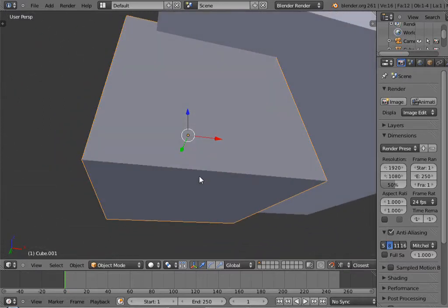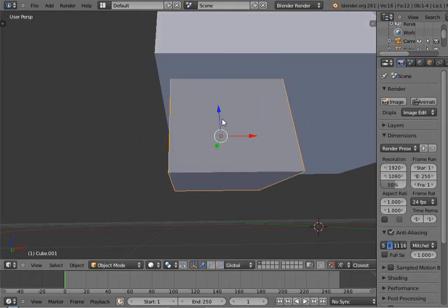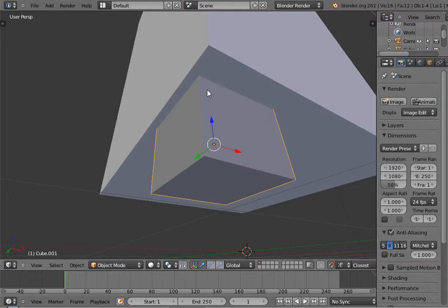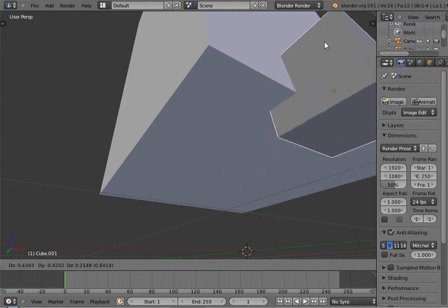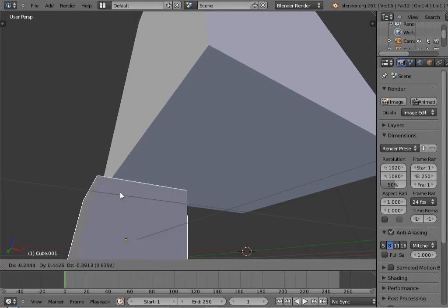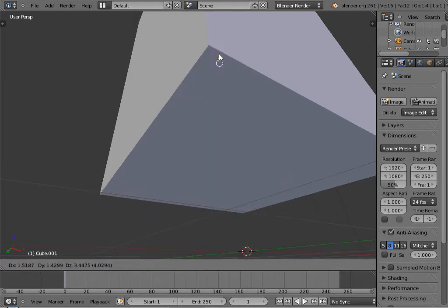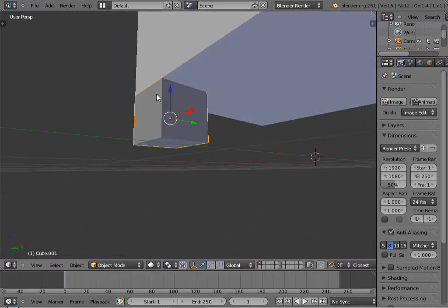Now let's zoom in on this object here, and you can try to move it around like this, but I find when you're snapping, the best way to do it is press the G key, which is for move, but you know, G for grab if you like. Press G and it's moving in all three dimensions, so it's a bit difficult to tell. But if you move towards one of these points, one of the corners, the vertices, it will snap. So there, that's very exact and nice.